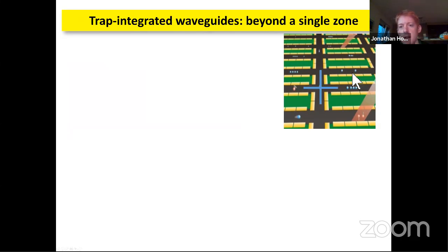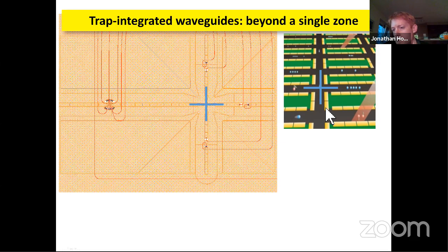One of the chips that we had back from the foundry in that last run includes a very critical region for trapped ions. This goes back to Elisa's question, how do you go into 2D? One of the ways that we think of doing that is having these junctions where we can move ions either that way or that way, and so things get connected together in 2D. This trap actually has such a 2D junction on it.